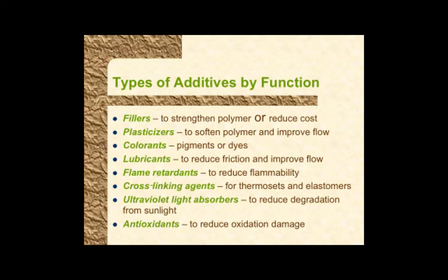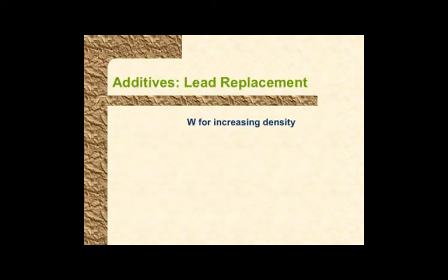Then when you began to add powders, one thing we said was we need a high volume fraction of powders in ceramic or metal powder processing. The second thing is these are more abrasive materials, and so those are some changes you have to make. You have a high solids loading, what happens? A high volume fraction of powder, what happens to the mixture?